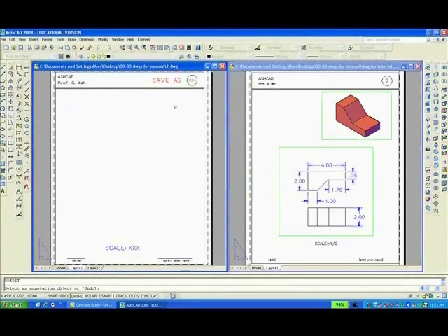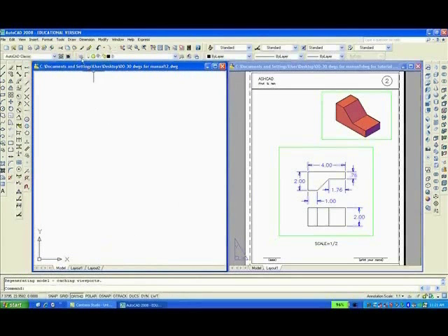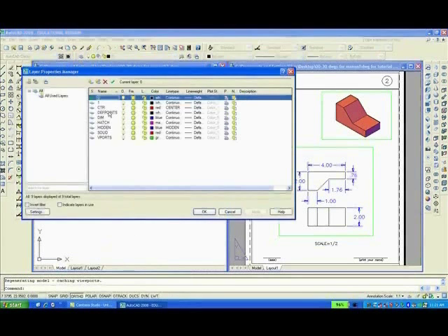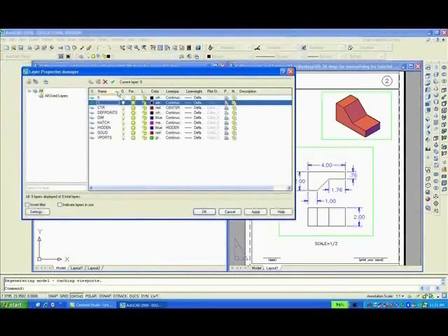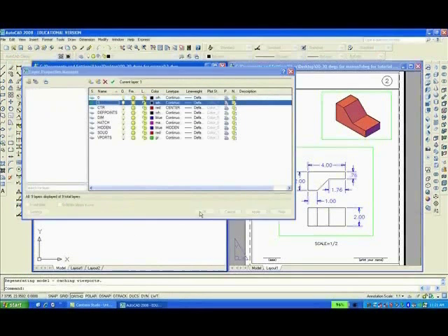Edit, ED enter, change the number of the drawing to 2. Go down here, the scale is also 1/2, 1/2. Then you go into model space, hit escape when you have to clear the command line. You move into model space, making layer 1 current. That's the layer on which to draw.